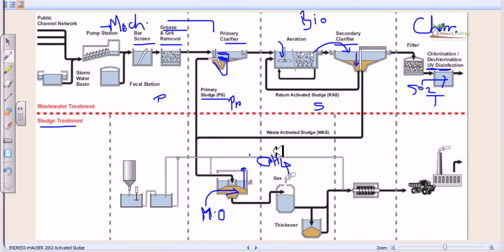So it is pretty good for us to utilize this kind of sludge digestion and the energy which is derived from the sludge digestion. Right after this sludge digestion, we utilize the sludge thickener to make the sludge thicken. So how can we make sludge thicken? We utilize sludge thickeners, and there are usually different types of sludge thickeners, like gravitational force, gradient dependent and all these different types.